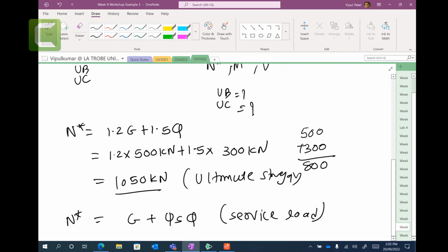This 500 and 300 is just a guessing business. The surveyor is going to tell you how many are going to use it. But in that guessing business, of course, you will think of your own benefit. You will not guess higher, because it will cost you more. Let's say you want to make a university, and someone wants to save money. Someone might say, in this room we have 50 students, but we will say 10. And the standard says, okay, I know what you're going to do, so let's add 20% for your dead loads and make it 50% extra for live load.